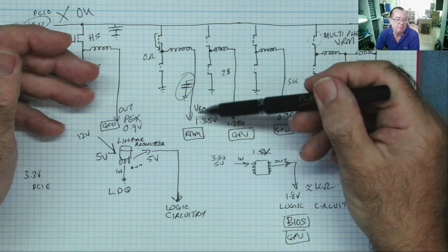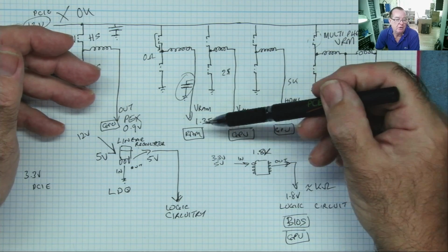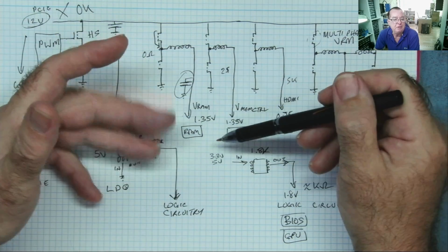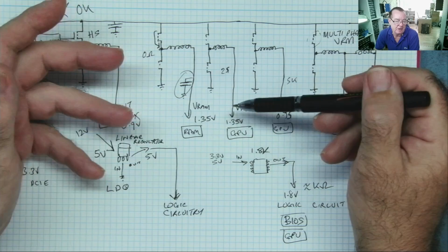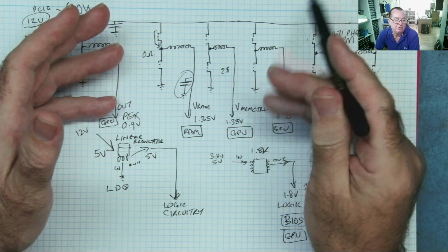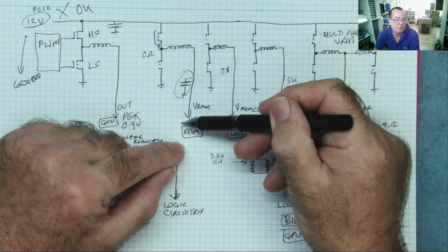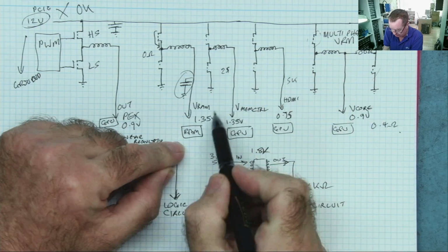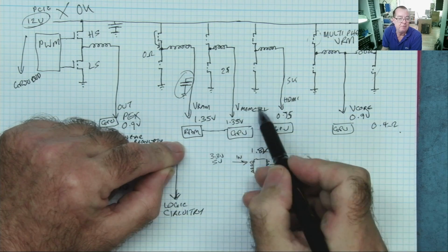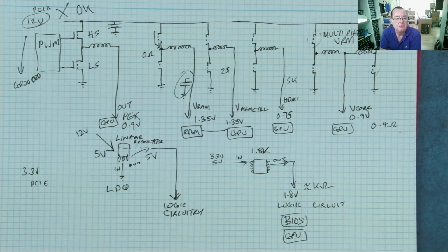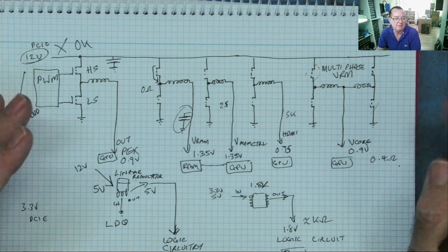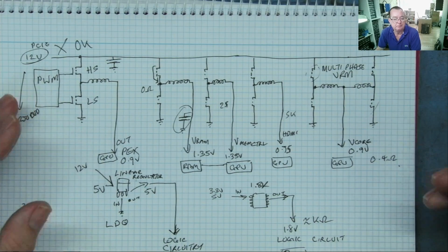For example, if the RAM reads short, you can be fairly confident that even if you take all the RAM chips off and change them, or change the short circuit ones, you'll still have a graphics card that doesn't work, because having a short circuit in the RAM, which is connected directly to the GPU memory control, you've probably got damage here as well. So you can see short circuits on graphics cards are very bad things, okay?